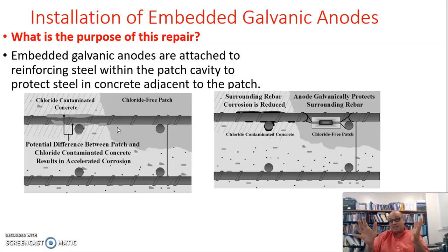That is something that you might be interested in addressing in one of the future presentations that we're going to assign. Another method is applying a zinc component, a sacrificial anode, to the steel reinforcement. This is an anode which is protecting the steel, so that when the corrosion comes, this is going to corrode, saving the rebars.